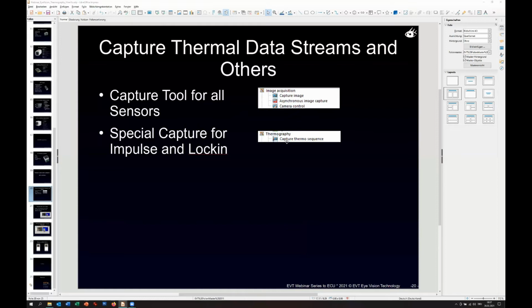For example, if you have a process like forming the dashboards, so the process has by itself process heat, and you could do this, let's say, impulse thermal imaging direct after the part comes out of the forming unit, and run the impulse thermal imaging.